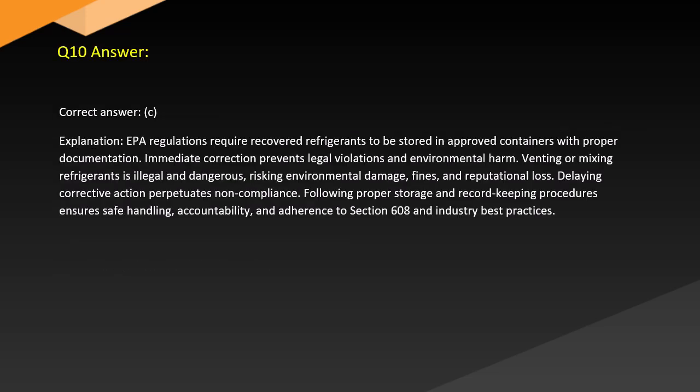Answer. Correct answer. See explanation. EPA regulations require recovered refrigerants to be stored in approved containers with proper documentation. Immediate correction prevents legal violations and environmental harm. Venting or mixing refrigerants is illegal and dangerous, risking environmental damage, fines, and reputational loss. Delaying corrective action perpetuates non-compliance. Following proper storage and record-keeping procedures ensures safe handling, accountability, and adherence to Section 608 and industry best practices.